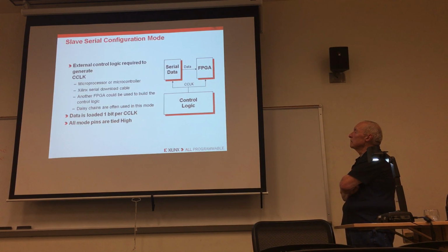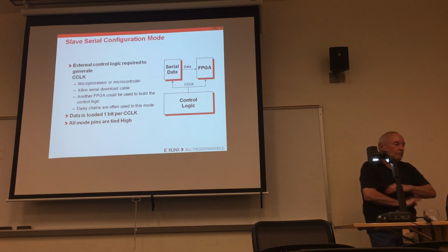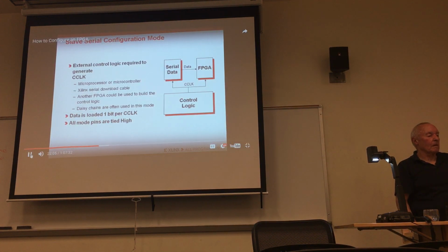The advantage is that the user could store the bit streams for multiple FPGAs in one external memory resource other than a flash PROM. And depending upon the...